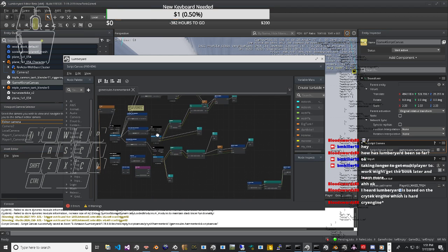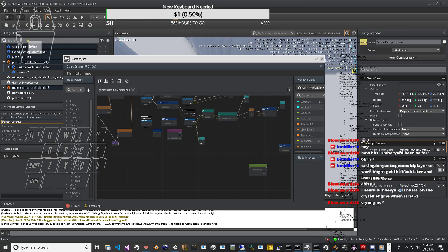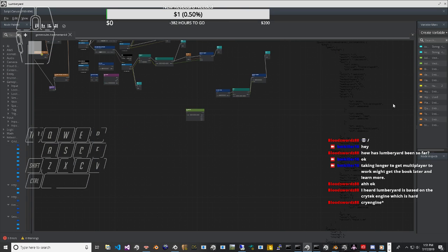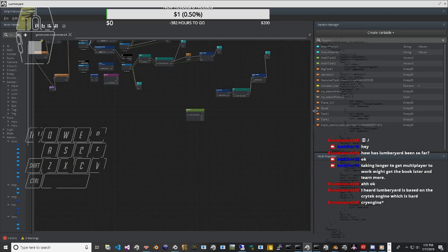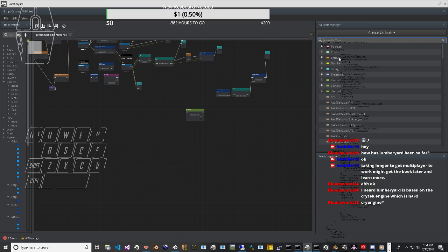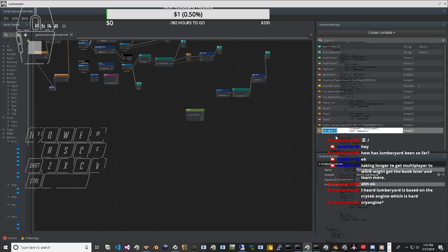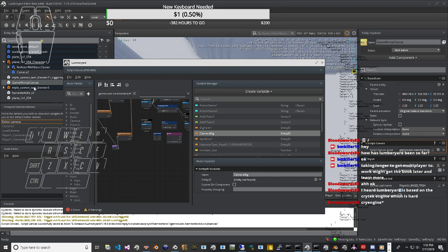The next coordinate frame is car, whose axes we write as x, y, z. This frame is fixed with respect to the sprung mass of the car, that is the body, with x running from tail to nose, y to driver's right, and z downward, roof through seat. Its instantaneous orientation with respect to Earth is the heading.